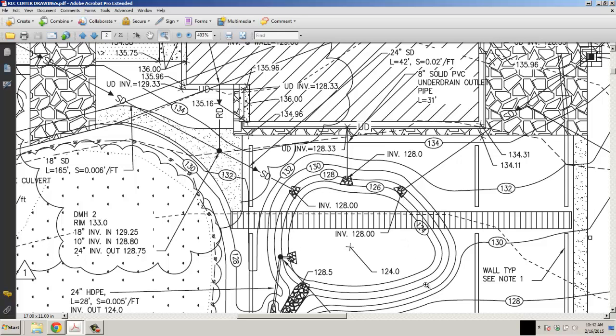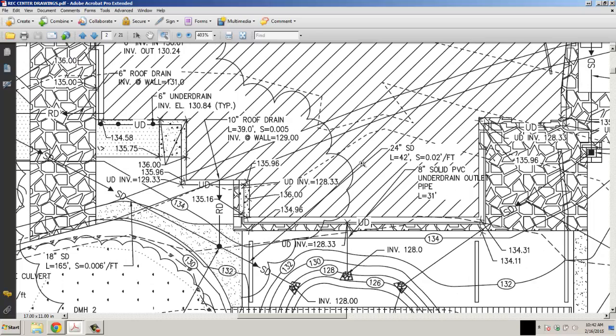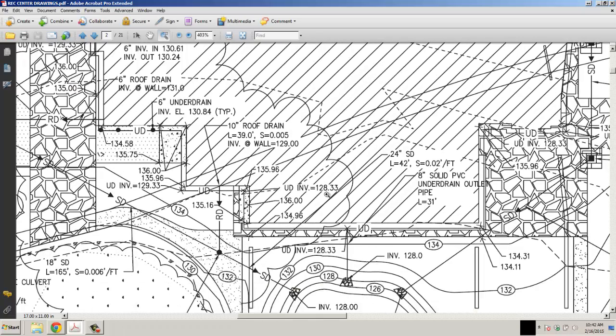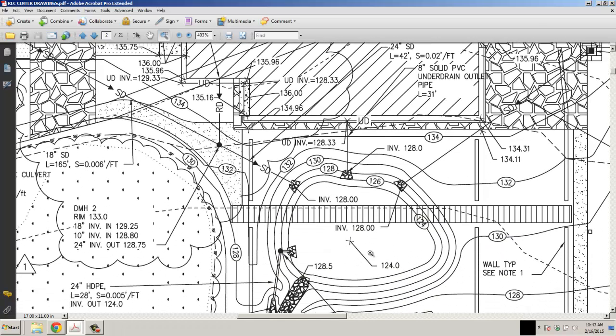Right down here we have what's at the south end of the rec center. This is just outside the swimming pool area. The site doesn't show that just yet, but we have a bioretention pond. So we can see our contours here for our grading. If you walk by the site, you'll notice there's a depression here, and that is designed to hold rainwater coming off the roof in the event of a heavy rainstorm, rather than washing out the culverts and whatnot. It's designed to hold excess water and allow it to drain out at a regular rate.